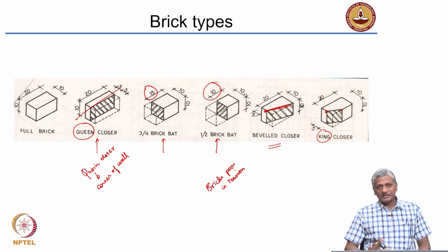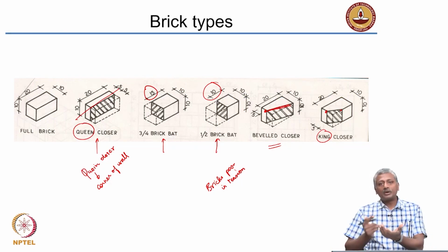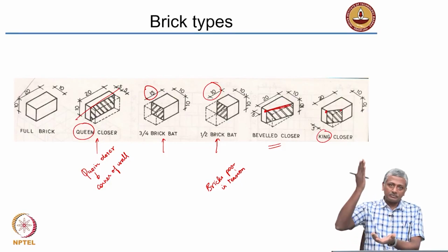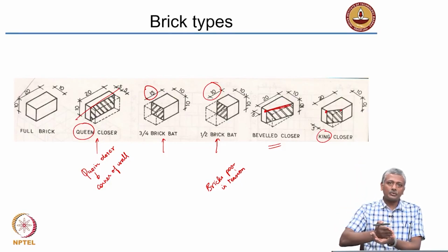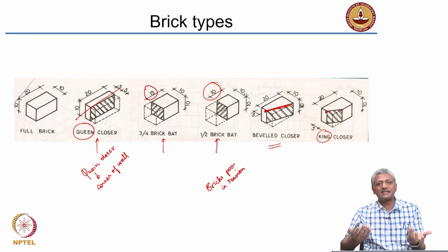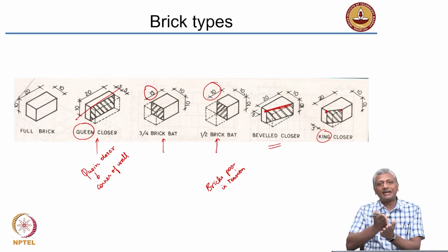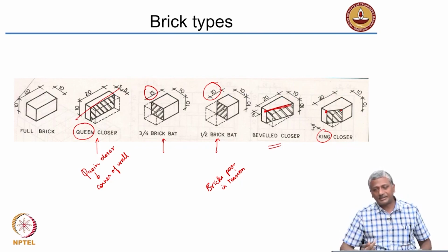Okay. As far as bricks are concerned, like stone or concrete, they are also very poor in tension. So, when you are trying to have a trowel to slice the brick, it slices easily because the trowel, the edge of the trowel puts the brick into tension. So, it is able to fracture quite easily.